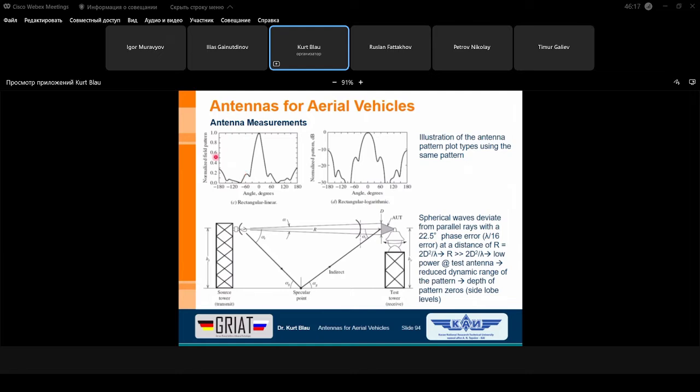If you scale this in the log scale, you can see that the resolution in the low area is much better. You can see the pattern in the logarithmic scale, and the two side lobe levels are in the graphic much higher. Minus 30 dB means we have a very small voltage here, and you can define this as the first zeros in the elevation range, left and right beside the main lobe.